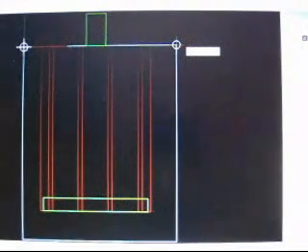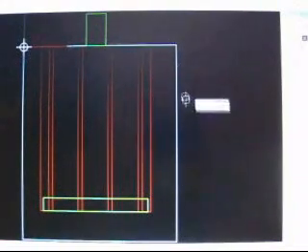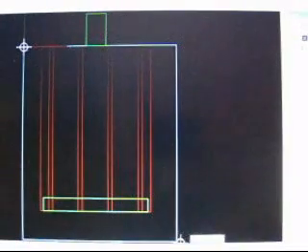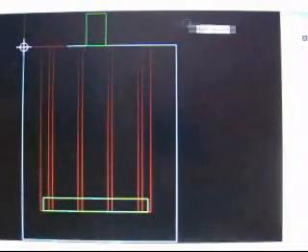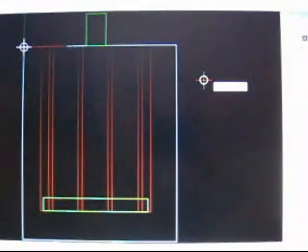But you have to take into account the bit. So let's say this cursor is a bit, like a 3/8 or a 1/2 inch bit or whatever it happens to be. If it's a 1 inch bit, obviously I'm going to be able to cut around that by the radius, so I'll be able to cut a 1/2 inch around my travel extent. So you have to add things up when you're dealing with that.